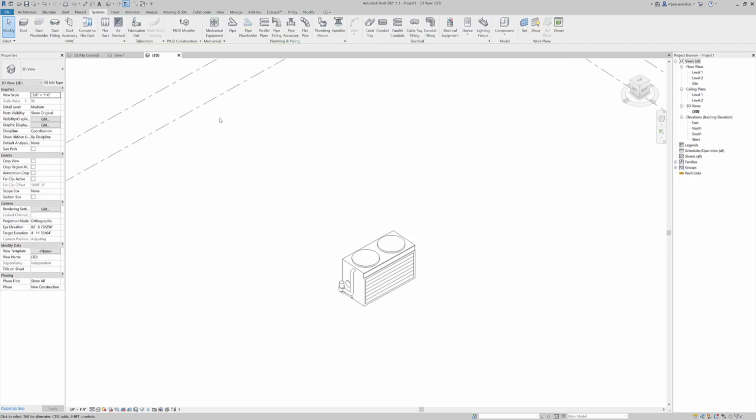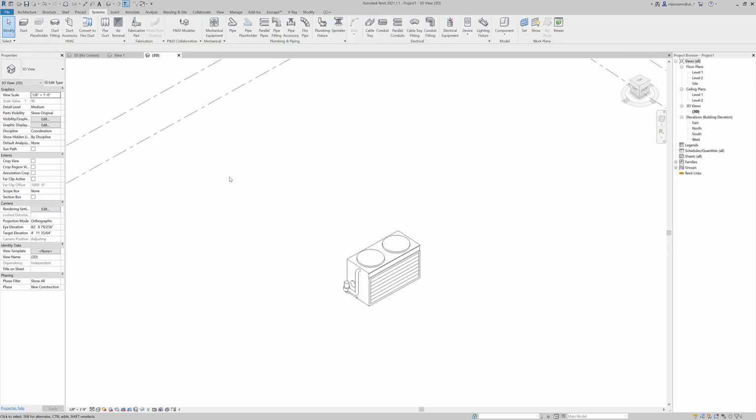Let's take a look at the next piece of mechanical equipment here, and those are the AHUs. So for the AHUs, we've basically recommended 3 different versions. The first is one big unit, which supplies your entire building. That's going to be a fairly large unit. Then there's a unit that is slightly smaller, which serves probably 2 floors, and if you have a 4 or 5 floor building, you'll probably need 2 or 3 of these. The last one is a single floor unit, so you'll have a mechanical room at every floor, and it will be a much smaller unit.